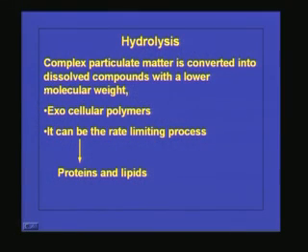First, the cells produce some extracellular enzymes. These extracellular enzymes will hydrolyze the big organic matter into small fractions. In hydrolysis, the complex organic matter reacts with water molecules. That is the hydrolysis process. The large organic molecule is split into small fractions, which can easily penetrate the cell membrane, and once inside the cell, it can undergo metabolism. So that is what is happening in hydrolysis.